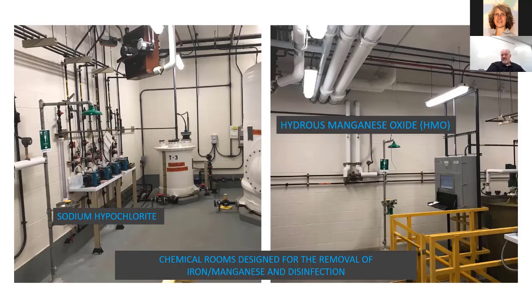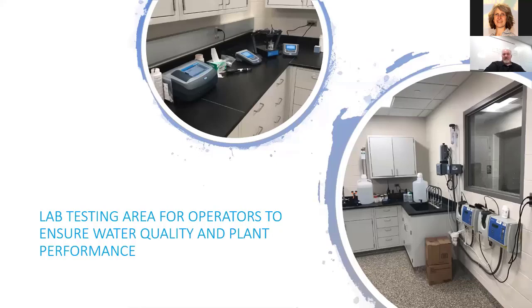We mix primarily the first batch at 10% for the holding tank or storage tank, and then for the day tank, we transfer into what becomes a 1% solution. Similar to the sodium hypochlorite, we have 2 pumps for redundancy, and one injects into a carrier water stream, which is then injected at the pre-filter.